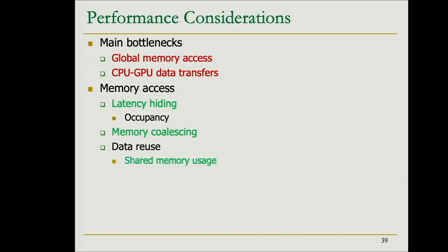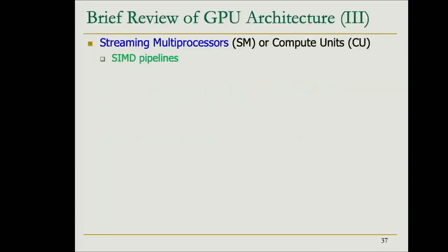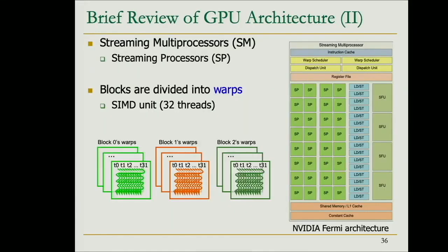It is an internal memory, let me go very quickly back. So it's right here. It's this shared memory that, maybe not in all GPUs, but typically is the same memory space as the L1 cache, and is internal to the stream processor or GPU core. So that's why all these units that we have here can access this shared memory, a scratchpad on-chip memory.